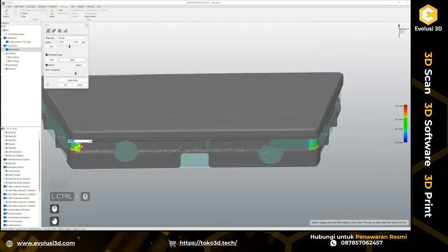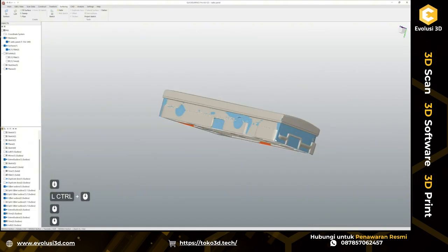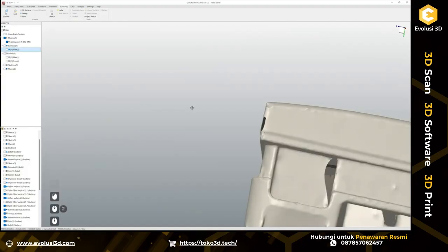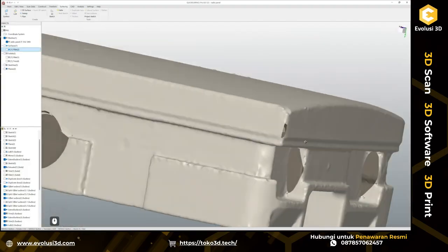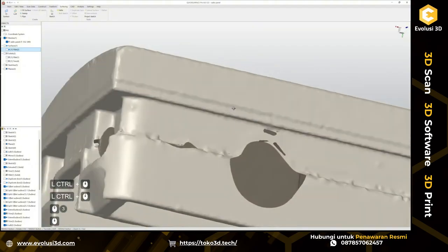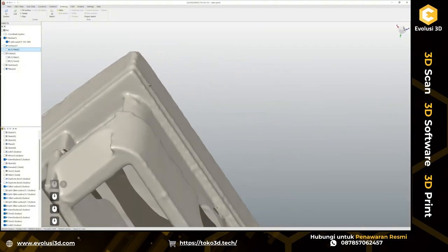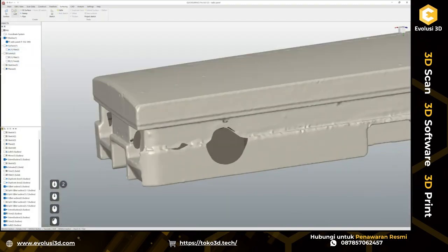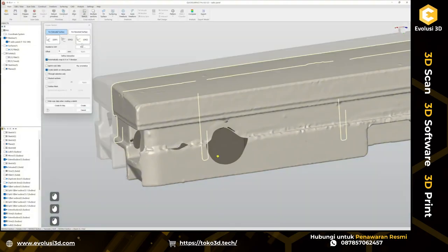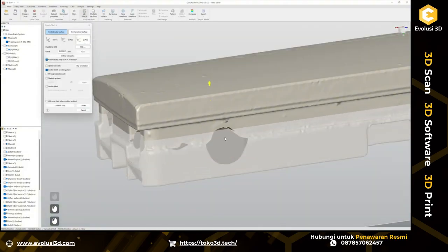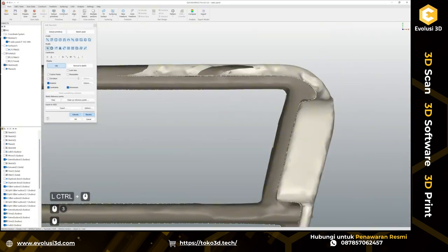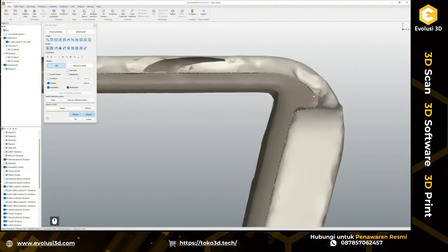2.65 or even more. Oh, 3 millimeters. Okay, good on this side. Let's see what's happening on the back side. So here we have something. That's not a complete fillet. So it seems I'll have to create a cross-section sketch here to define this shape here.